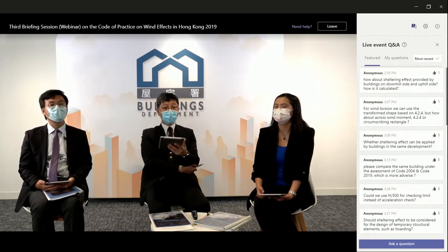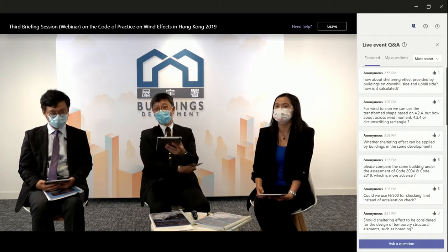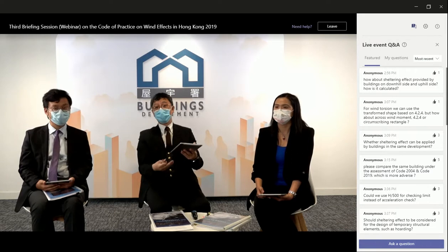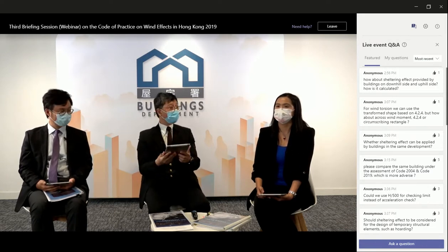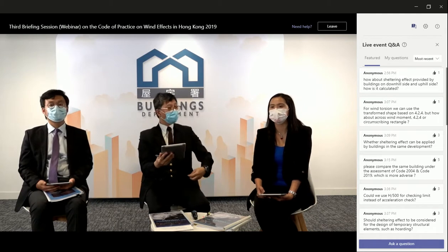Maybe I simply just add to that: the 2019 code is more scientific and also gives a more procedural method to calculate a more realistic wind load based on the existing condition, which is more advanced than the 2004 code. Yes.